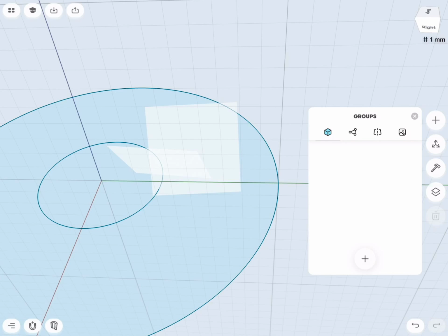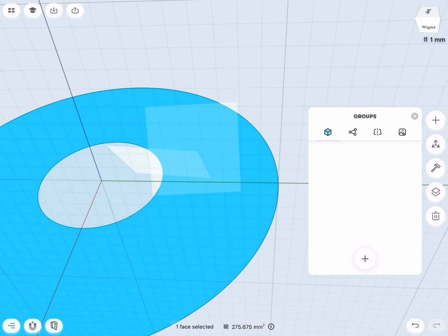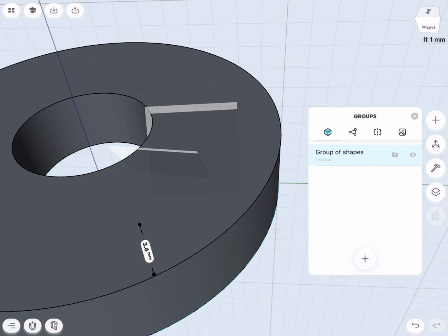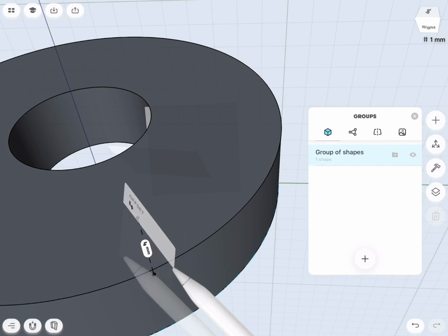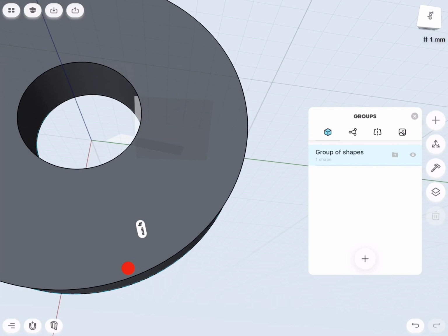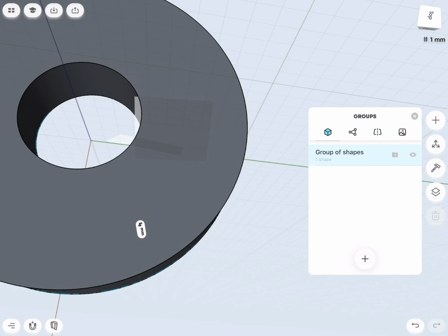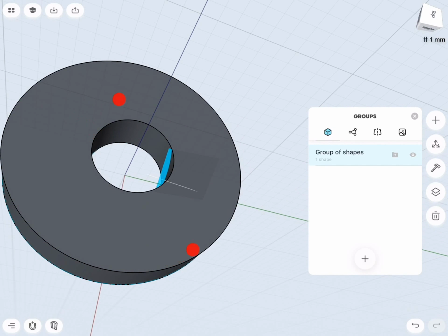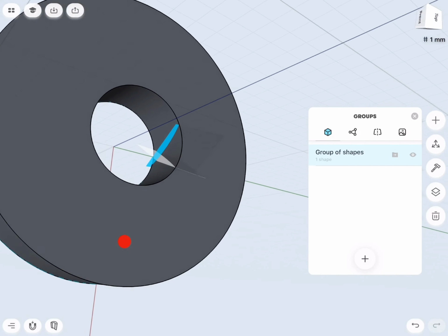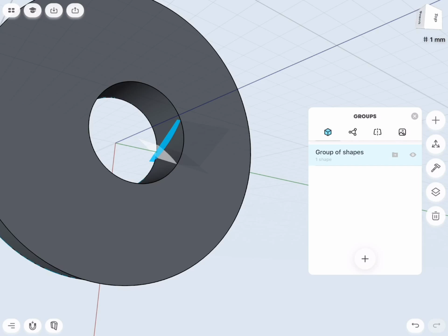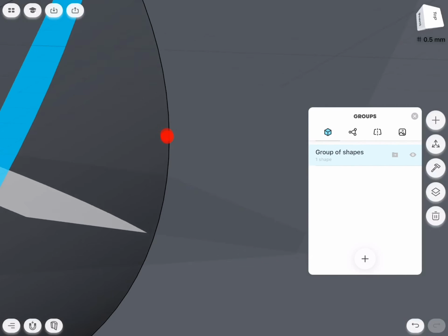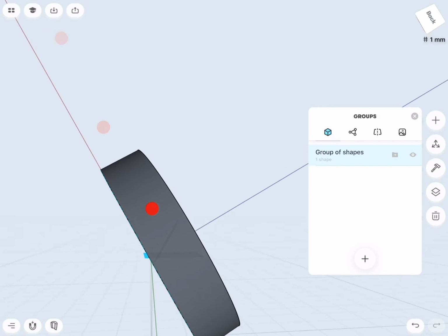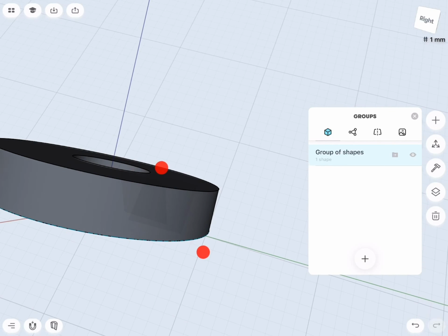From there, we're actually going to need to make a solid shape that we're going to cut using the construction planes that we have. So I'm going to make a 4mm donut here, and I'm going to now sketch on each one of these planes and essentially use that sketch to delete the areas of this donut that I don't need in order to make one tooth. So I'm going to select a sketch plane, I'm going to double click on it with my finger, and now my sketch plane is with my construction plane here.